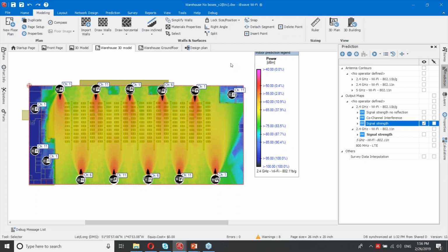So it operates at the frequencies that were designed as LTE frequencies by 3GPP and is only open to the LTE protocol to be run on that frequency. So when you talk about CBRS, you really are talking about the LTE protocol running on a managed spectrum, which is neither licensed nor unlicensed, but something in between.